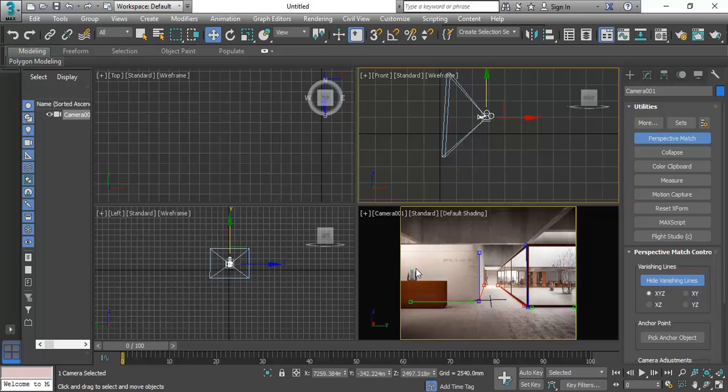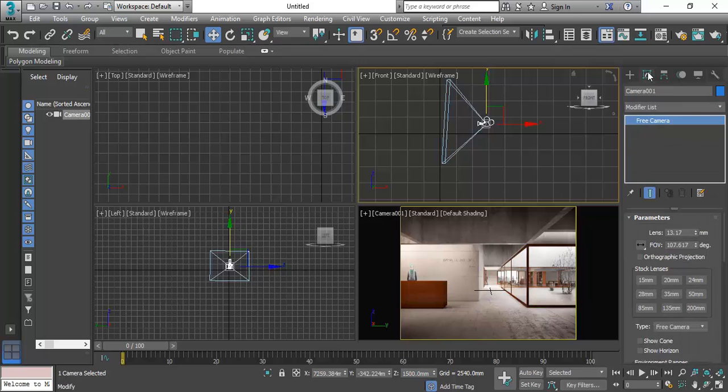You can tell just by eye that it's taken roughly at a normal eye level. We've got a human there with the eyes roughly in line with the horizon, so that's fairly standard. Looking at the coordinate down there, the Z value, 2400, is too high. Human eye level is around 1500. So I'm going to drag that slightly down until the Z value is lower. 1480, that's pretty close. You can always type in 1500 there if you want to, or 1600.